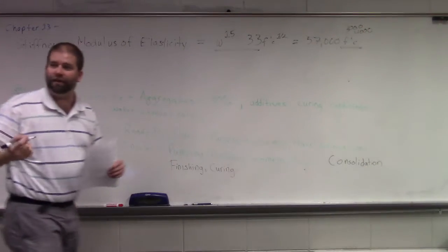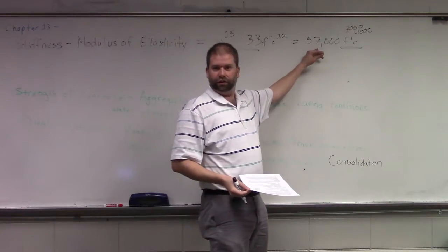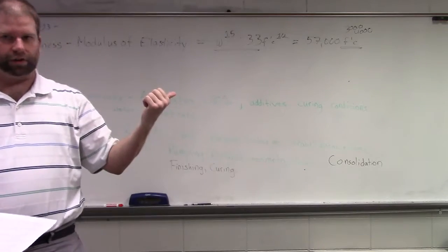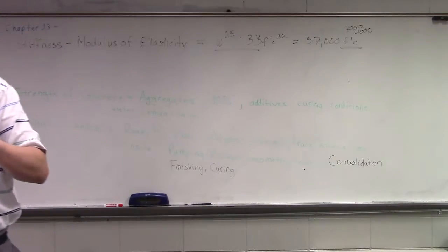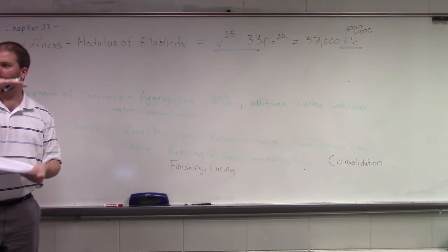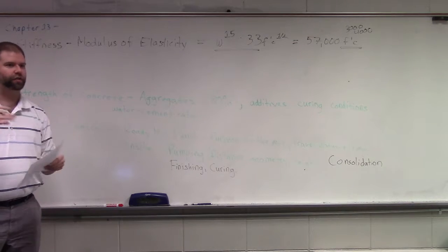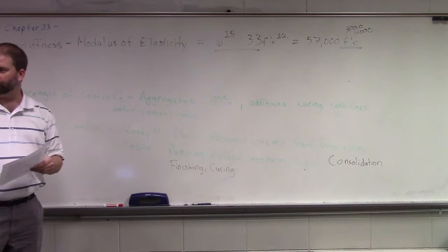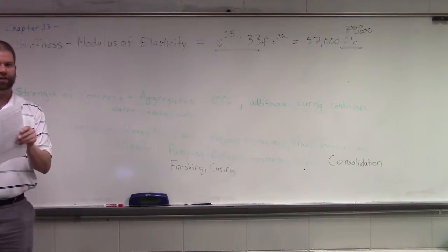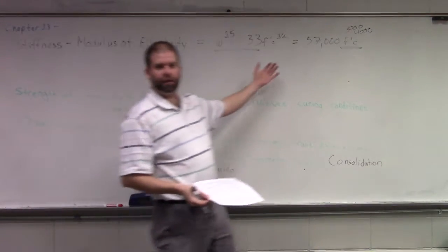From the standpoint of evaluating a mix, a calculation is not sufficient. It's a test that we have to run in the lab. It's very similar to the compression test where we take the cylinders and crush them. Rather than actually crushing them though, we deform them about 0.05 inches, so 1/20th of an inch. Measure that strain, cycle it over and over and over. We measure as we're compressing that 0.05 inch, how much it's expanding in the Y dimension. And then we actually determine that number.